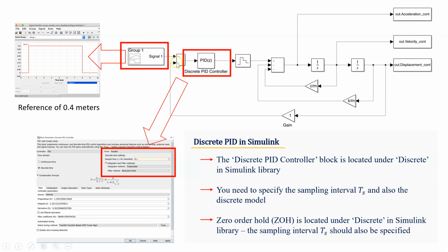And what I'm doing effectively to form an error is taking the reference minus the measured output to form the error. So that forms the error there. It's negative unity because we're assuming an ideal sensor, so in this case, 1. And here you can see in the feed forward path we've got at the moment a PID controller. And you can see here it's in the Z domain.